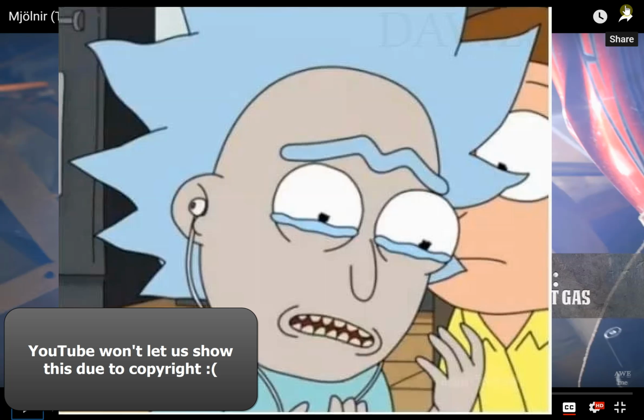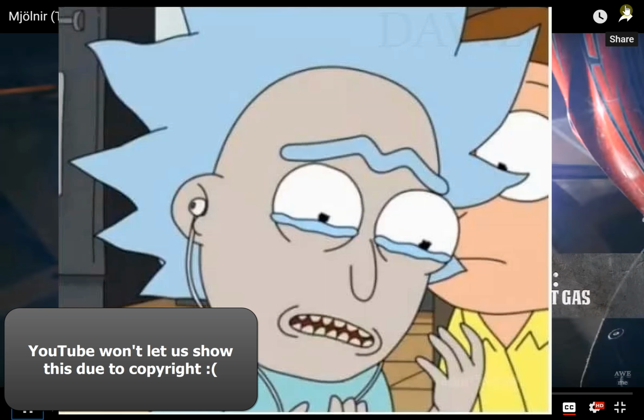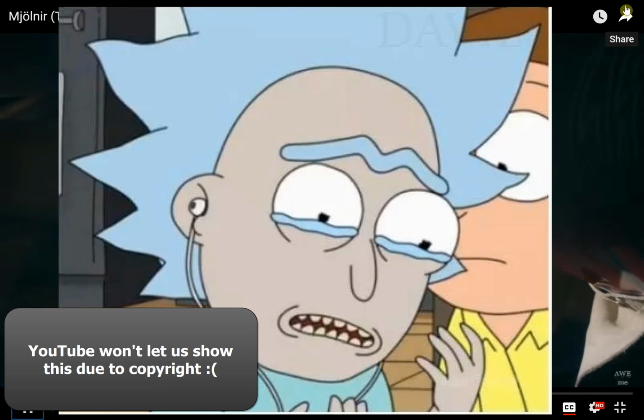Yeah, Ashton? So the tungsten, because the point is inert gas, because you don't want the gas to react with the metal you're using. Yeah, if you do this without what's called a cover gas, in this case it's argon or something, if you melt metal, especially something like a steel, it's going to oxidize. If you get oxidation at this junction, that junction's going to be weak and it's going to be prone to failure. But if you're blowing argon over it, then you're pushing all the oxygen out of the way so that you locally melt it and there's no oxidation, or there's less oxidation, okay? So that's TIG welding.